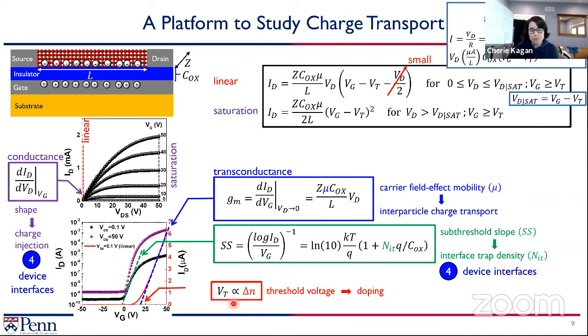these nanocrystal films. Of course, if we also dope the films, it'll also affect the off current in these devices, because the more charge that you have by doping, then you'll already have a path for carriers to transport. So there are opportunities to learn from the characteristics to understand transport. And then, of course, all of these metrics are device metrics that are important for performance. So I'll also introduce this current modulation between the on and the off state.